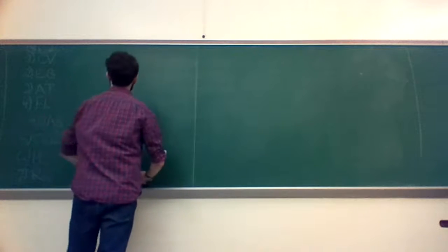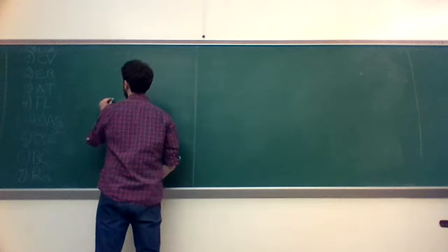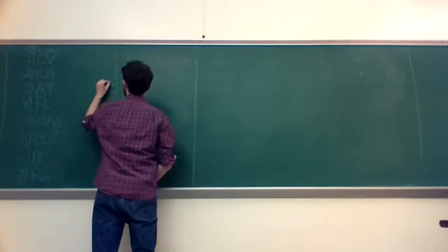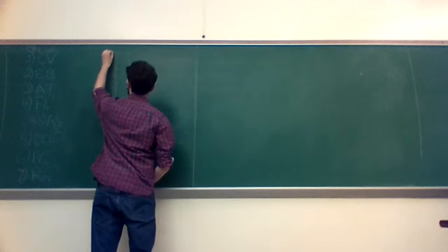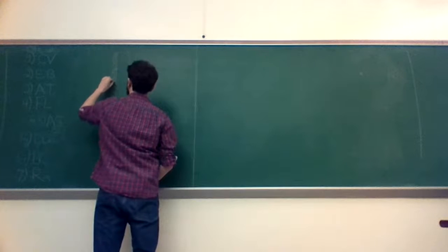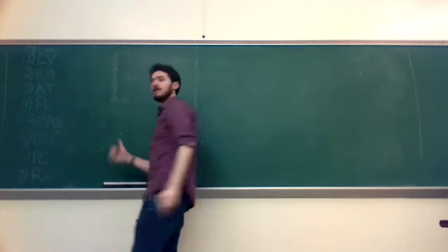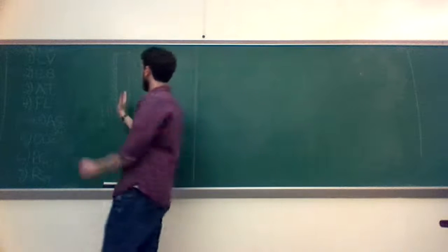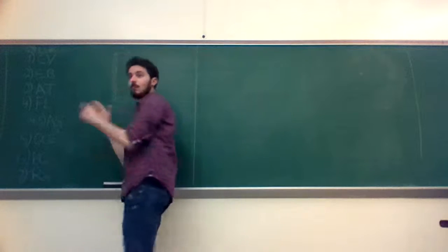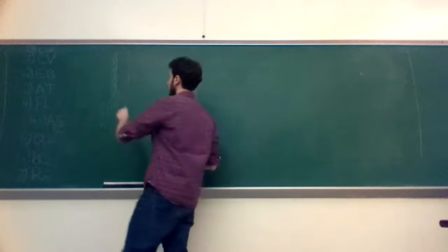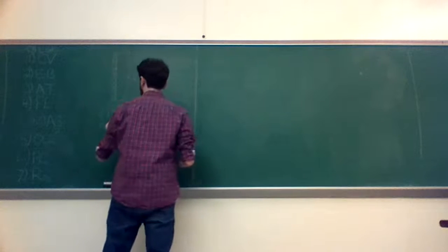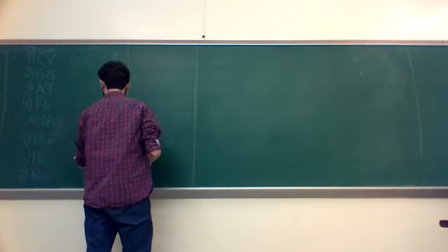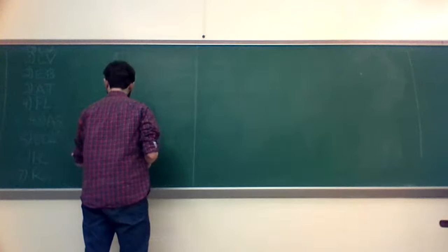And we know that from the middle, it's the equivalent of having an insulated boundary condition, because there's not going to be any heat flux past that center point. So if originally this thing was L wide, the thickness of the slab, now we're dealing with half a slab. The length is L prime or L star, which is L over 2.